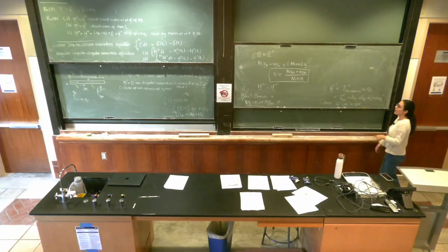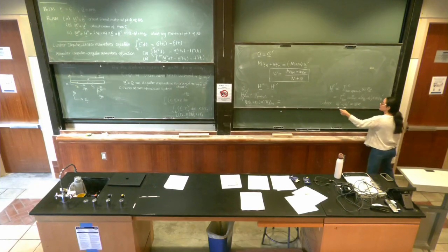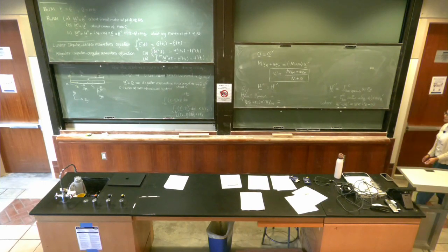Omega, the same angular velocity as the rigid body, crossed with RB minus RC. So for the angular momentum of the system, I can do it in two ways. I can consider a new rigid body, the bar plus the particle, or I can still consider the two bodies to be separate, but the velocity of the particle can be calculated from the fact that now it's a material point on the rigid body, right?